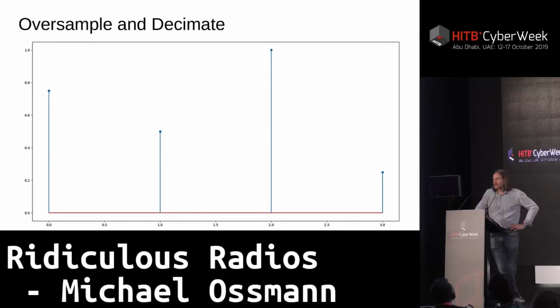And what I'm showing you here is kind of the crudest example. In practice, what people do is not this very crude way of just averaging 2 samples at a time. They do something slightly more sophisticated where they take a bunch of information from many more than 2 samples at a time and use a low-pass filtering technique.